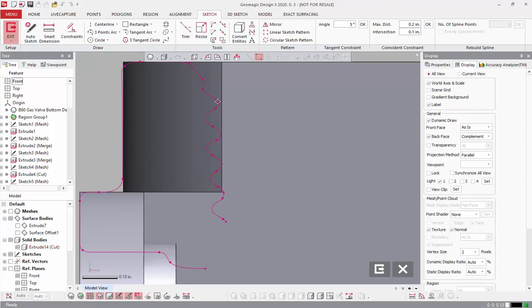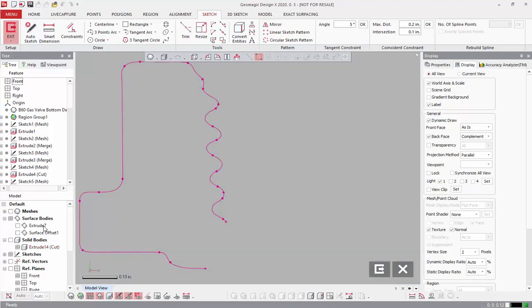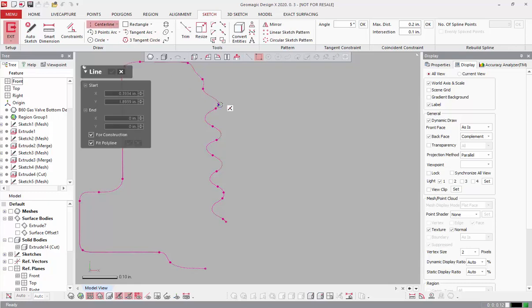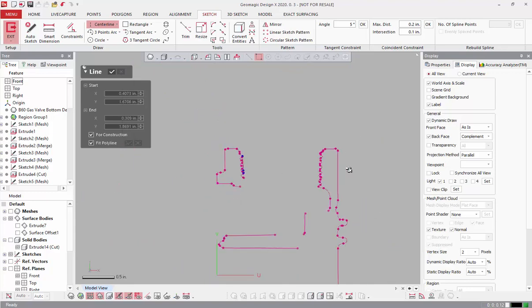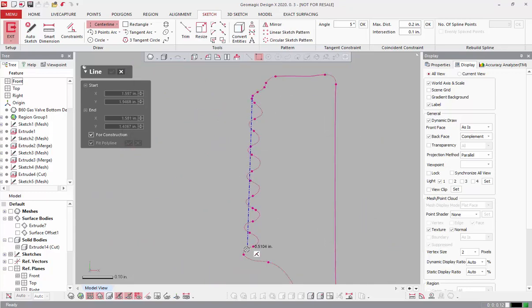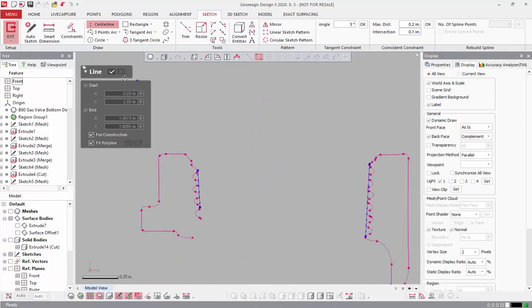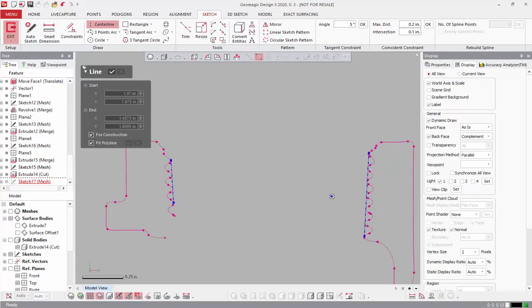This is actually interesting because we can see really quickly that this is not a constant radius part. I didn't even notice that when I did my extrusion. I didn't really check the color map after I did that cut. So we know, and this is fairly common here, this is a gas valve part. We know that these parts are tapered threads as they screw into one another.